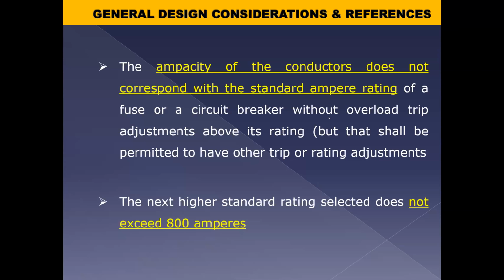Okay, sir. So if the breaker table doesn't match, we adjust the cable, or the cable to the breaker. Okay, sir. Yes, or you can employ adjustable trip units, sir. Whichever is cost efficient of those options. Research first before you make the final selection. Compare the adjustable trip units just to save on cable cost. That is where your engineering decision comes in. You already know the strategies.